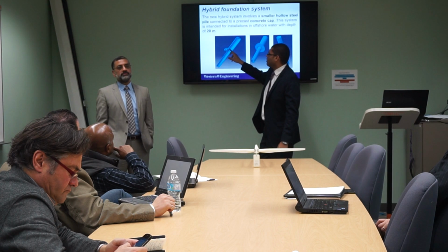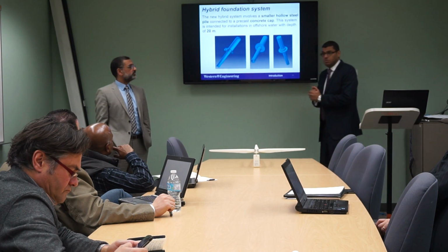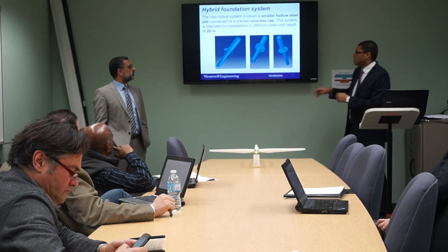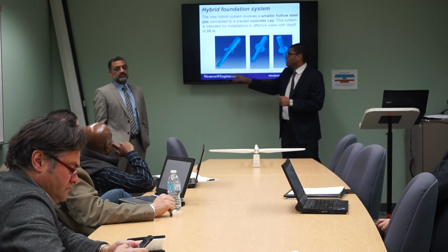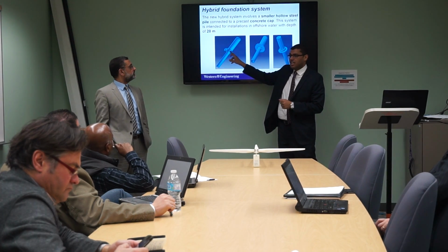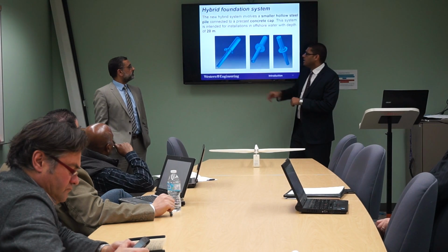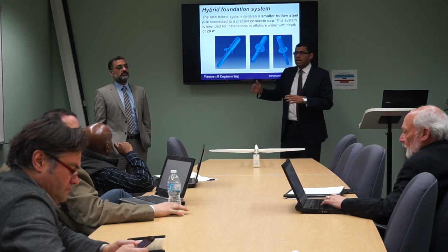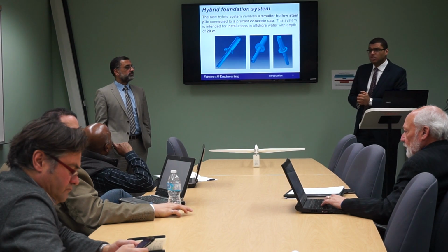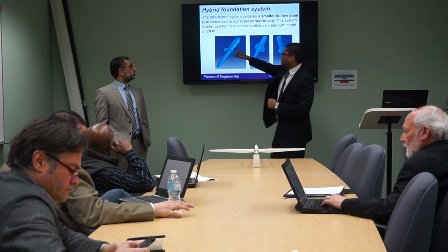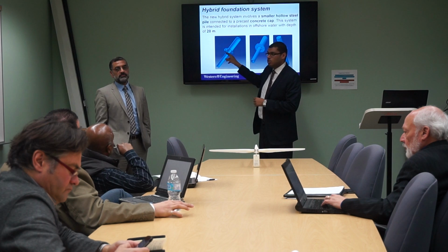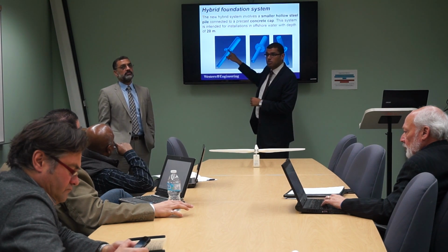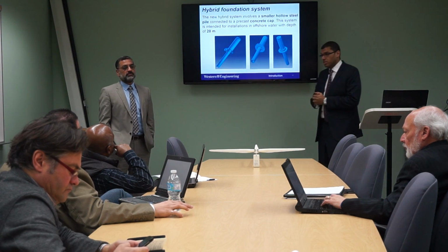So the connection here, we didn't focus on it because it would be out of our scope. We were studying the behavior mainly. But stresses here have been studied, although it's not included in this connection, so it was safe. But for the connection itself, according to the DNV code, we need to have some shear connectors between these parts because it's concrete and steel. So we need shear connectors to be able to grout all these parts together with precast concrete.